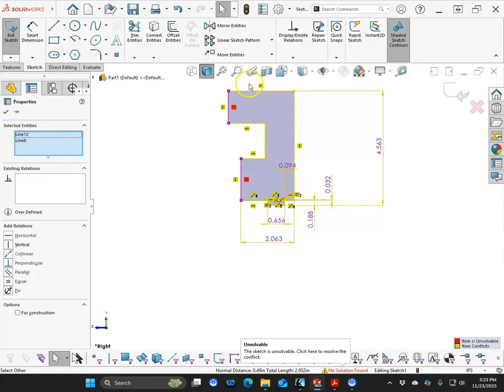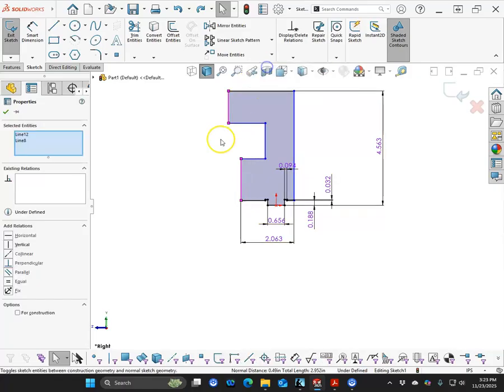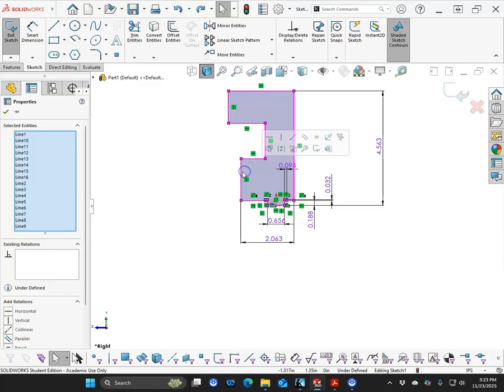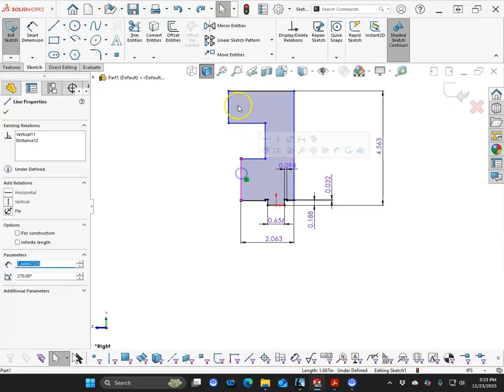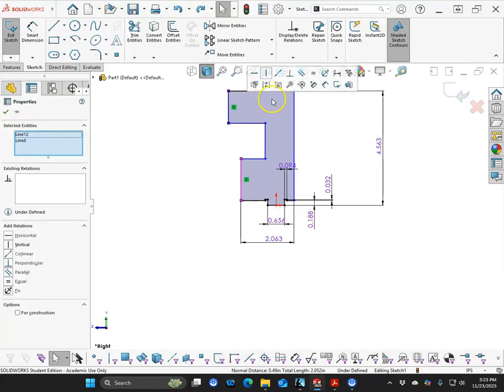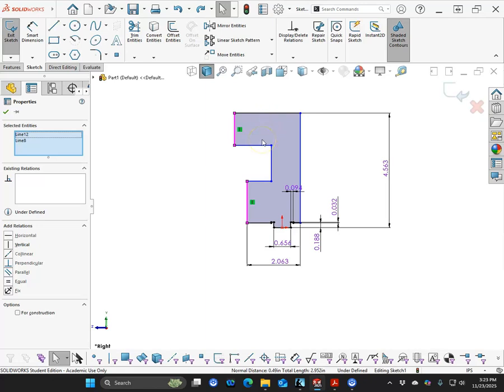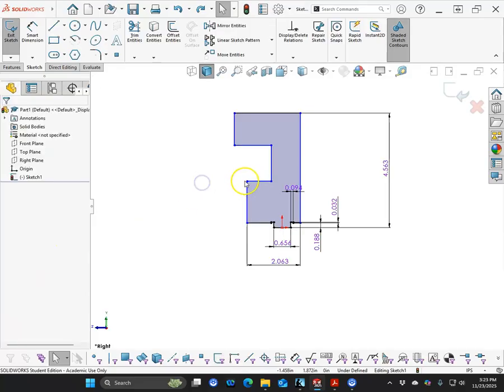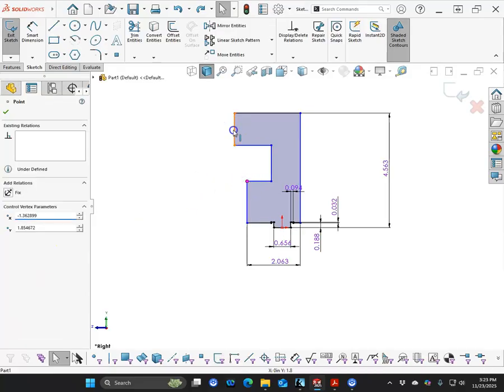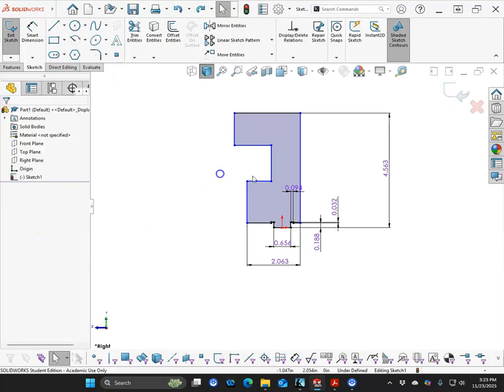Nope, that can't be horizontal, so Control Z, switch it to, oh, no, they already are vertical. I need collinear. All right, so just a quick review is that when we go line in line, those are going to be collinear. If we go to a point in a line, that will be coincident.